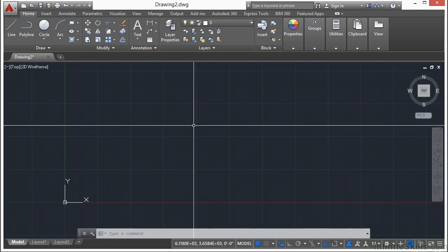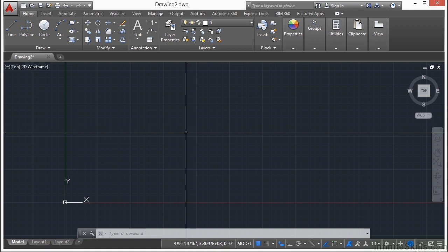Well, now you can draw lines and polylines, so now you need to know how to draw circles. Circles are used for many things. You can draw a hole, fantastic design, a wheel, a gear. I can go on, but you get the idea. A circle is a very simple thing. In geometry, a circle is defined as all of the points that are equidistant from a single point. So to draw a circle in AutoCAD, you use the circle command.